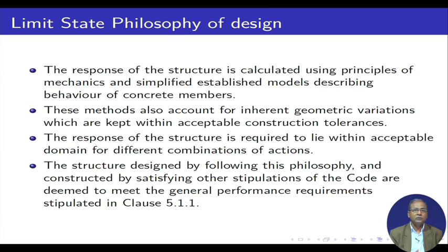As I pointed out, we assume that earthquake load and wind load will not work together. We can take them together for important structures, but it will be a very rare situation, and in that case we can omit the combination of earthquake and wind taken together.